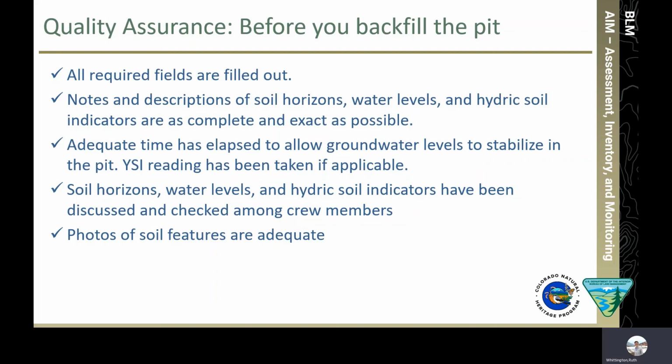Before you backfill the pit, verify that all required fields have been completed and that descriptions of each horizon are detailed. Review the soil photo to ensure the soil face is clear and includes a measuring tape and horizon markers. After verifying the soil data sheet is complete, fill the soil pit back in with the excavated soil.